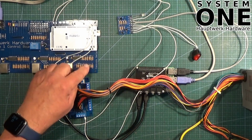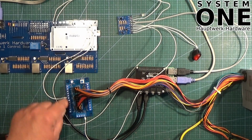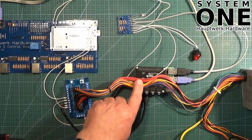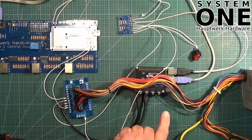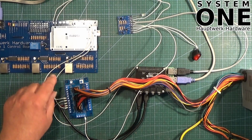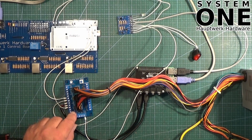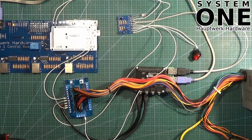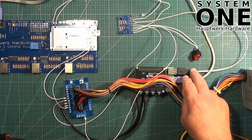And you could argue, well, it's going to know that anyway because it's getting 5 volts from the power supply. However, when the Raspberry Pi shuts down, it will turn off the USB, which we then sense, and we use the fact that that's happened to switch off the power supply, because the Raspberry Pi obviously won't directly turn off the power supply. So that's what that USB connection's for.